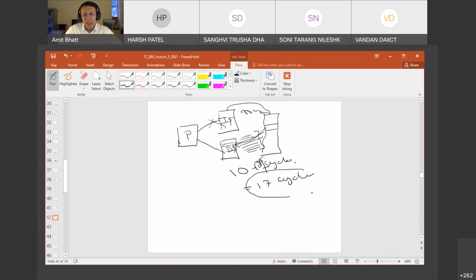So always remember this. When I say 10 cycles to go from here to here, those 10 cycles are actually used for locating that particular block and also bringing in the first batch of the data. And the first batch, how big that batch is, all depends on how many parallel lines there are. So here there are 64 parallel lines. That means 2 32-bit data can come at a time. And then in the next cycle, another 2 will come, and in the next cycle, another 2 will come, and so on and so forth.